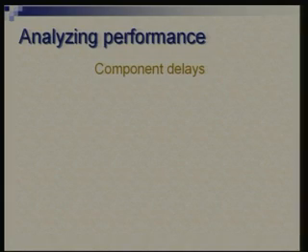Okay, having done that, now let's look at what good work we have done. Okay, we have got a design now. How does it fare in terms of performance? So for doing so, we need to calculate the delay and their impact on the overall clock period. So first of all, let's look at the component delays so that we will build it bottom up. We have register, one register in this case PC, for which we will assume that delay is 0. Actually, just to simplify the analysis, we will look at the delay of some prominent components, take them as non-zero, others we will take as 0.